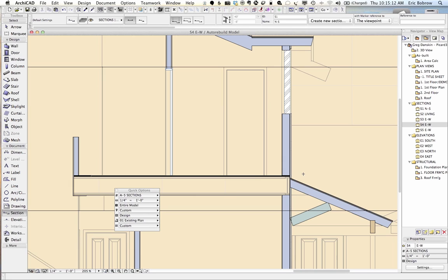I think it may be simpler in terms of your mental calculations for window heights, but since you have the option in general to reference the windows and doors relative to the story, it could work the other way. So it depends upon the way that you're constructing your model. For now, I'd say for you, you've got enough to learn here.